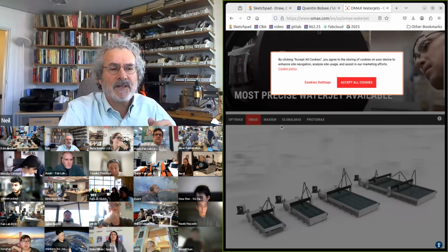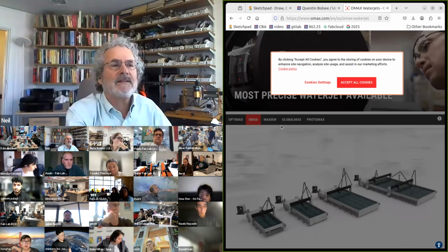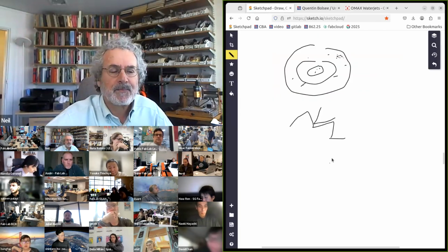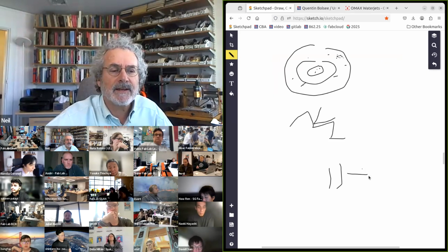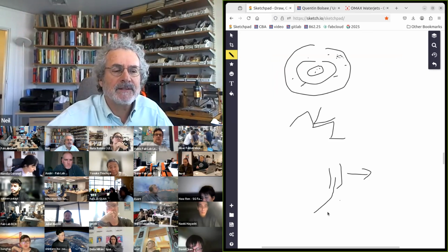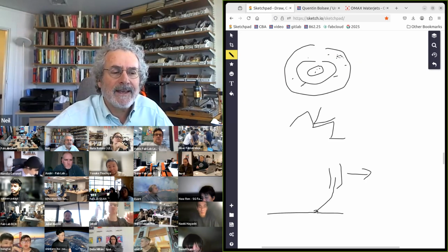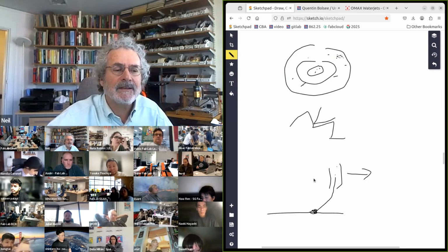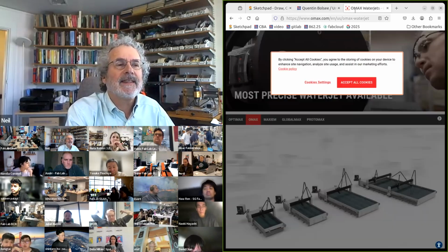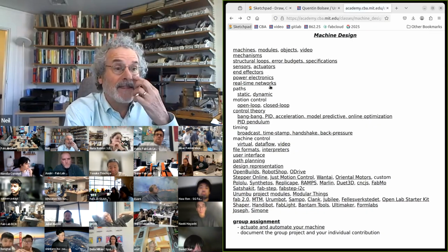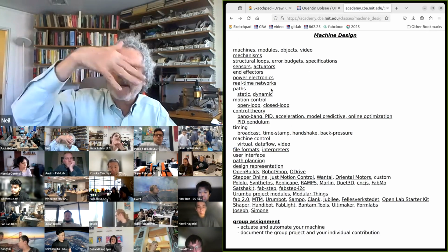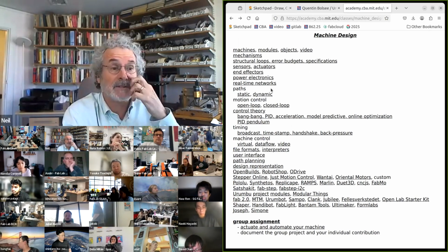This is a water jet machine. When it machines, the head is moving. There's a jet of water coming out that bends. And so where it hits is not where the head is, but where the head was. So for a machine like that, the path is dynamic, not static. Part of using it is you need to pick a path that anticipates how the machine is moving.